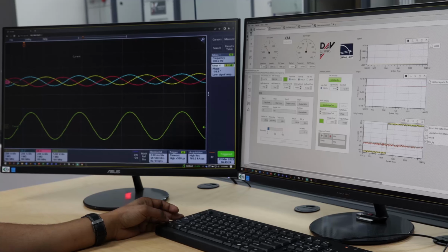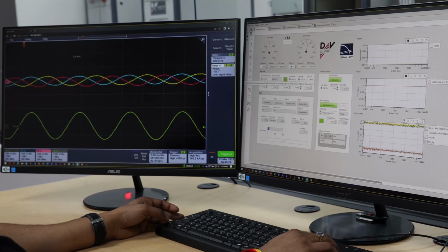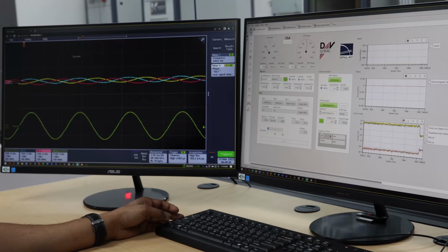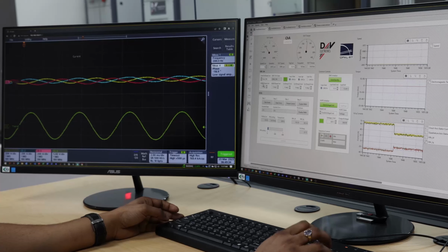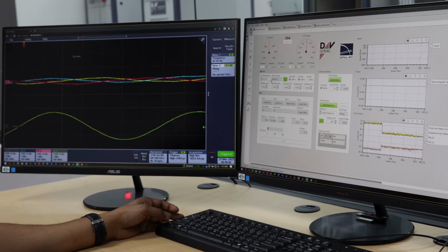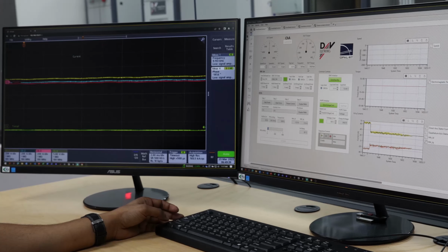The second test procedure that we will run is stall torque. So I will reduce the torque to 5% and take our speed down to 0. As you can see, we're still generating torque and the DUT is still reading a torque. The third procedure that we will run is inserting a drive cycle and controlling it through the sequence control panel right here.